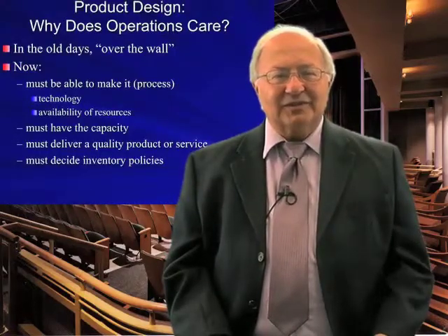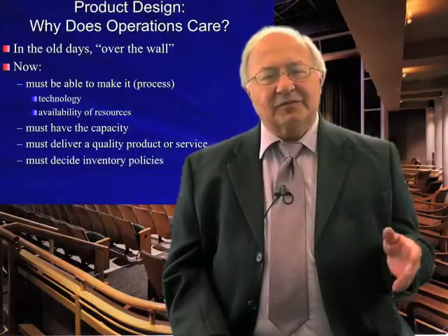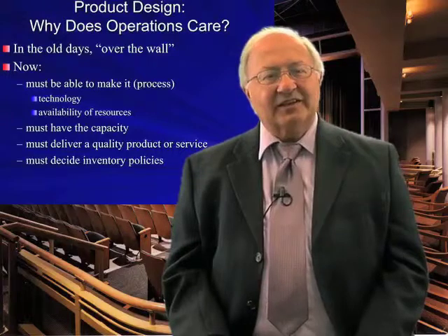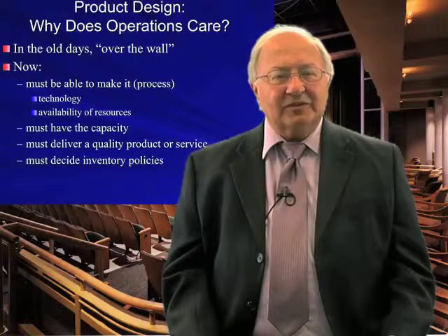The over-the-wall concept means when somebody designs something without participating in any other input, they complete their part, throw it over the wall to the next guy, and each person works independently. Well, you never know whether it's going to come together until the end of the process. And if it doesn't, you have to send it back and redo it, which is a very expensive way of accomplishing that. On the other hand, by working concurrently, you're bringing in inputs in every step along the way and avoiding some of the redo and quality problems that you might have.